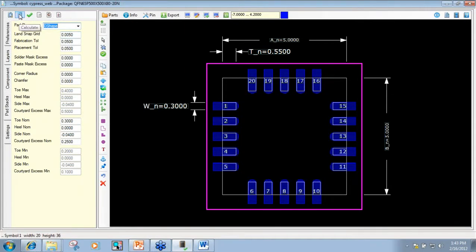So depending on your host CAD system, there might be certain types of pad styles that are going to have to get created as shapes, and we handle that all automatically. So if we exported this right now, a D pad is not a supported Allegro footprint style, so we would just create these pads as shapes, as well as the other information for paste masks, solder masks, etc.